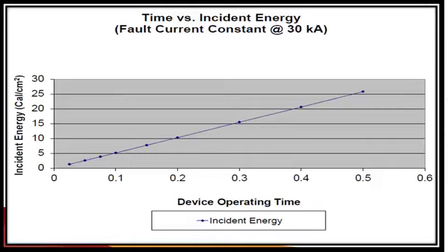Now I'm a consultant, and I have designed an electrical system. You people are basically my client. I have come to you and produced my design for approval. You identify as a CSP that at a particular location, the incident energy is 25 cals per centimeter square.